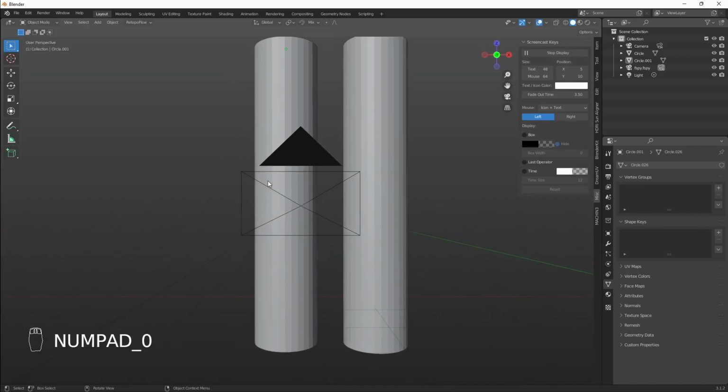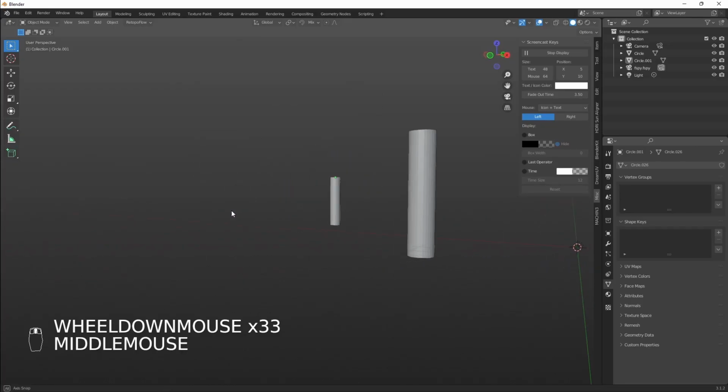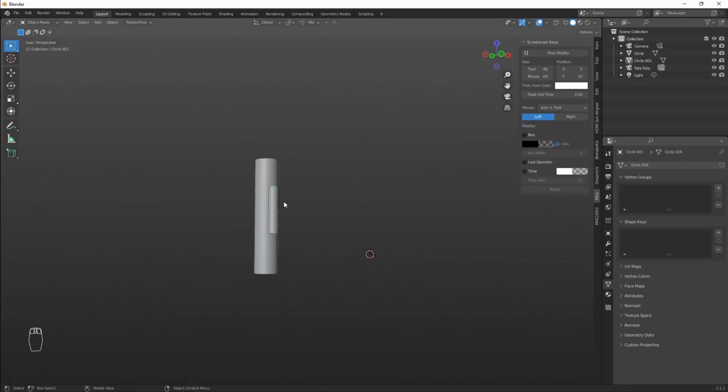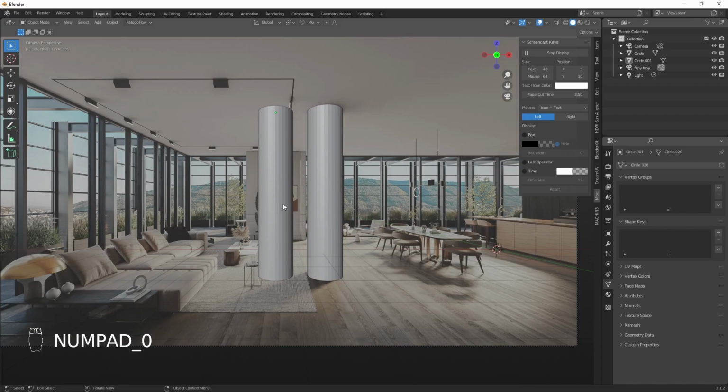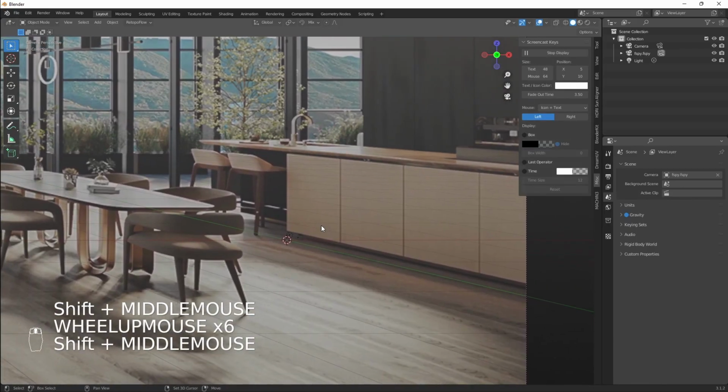But if we switch to the 3D view and look at the scene from a different perspective, it becomes clear that none of these are true. So, like it or not, it's impossible to determine all three coordinates from a flat image. You need to know at least one to get the other two. This is why we need the origin. It's the center of the scene, and because it's attached to some objects, we know that these objects have one of their coordinates set to 0. In our case, these are the floor and this side of the island.